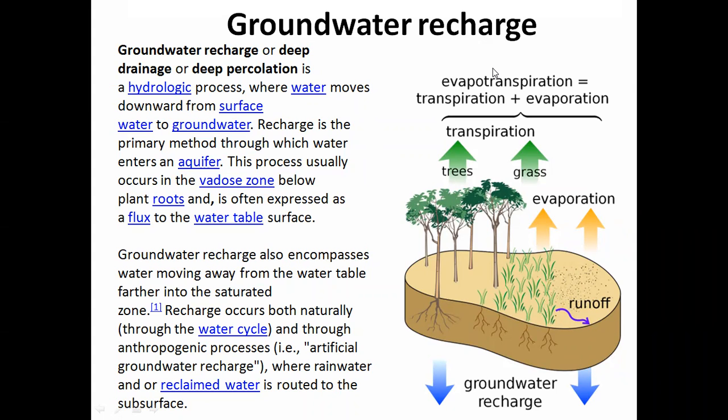From that, you try to create some flow, or some rainwater harvesting, like that. You try to give the point directly to the borewells, so that your borewell groundwater also gets recharged. Okay, so that is two ways. We will see more ways.